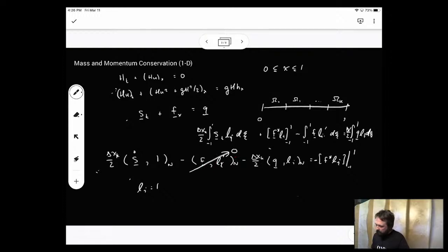Okay. And then on the right-hand side, I get the average value of the source terms. And then over here, I get the fluxes at the boundaries. And again, because now I've got a polynomial of degree n inside of here, which is still exact, and a polynomial of degree n over here, which is also still exact, I can actually rewrite this as the equivalent of doing S dot 1 in the continuous form.